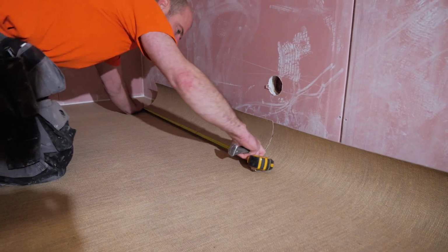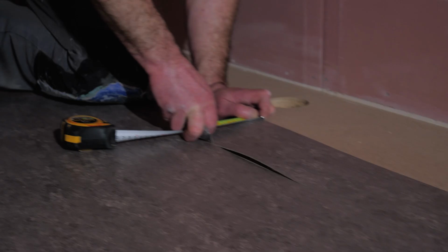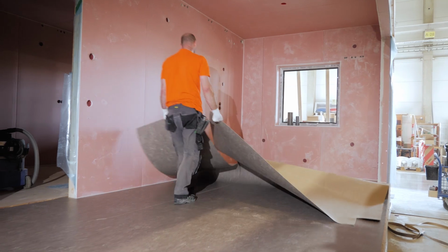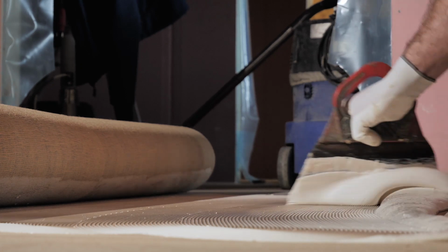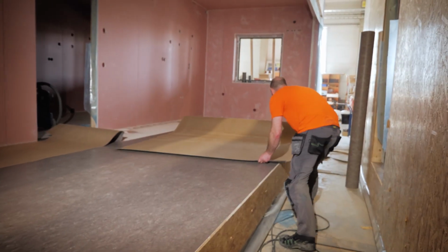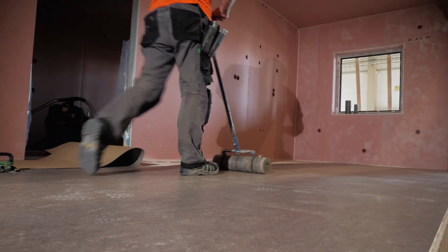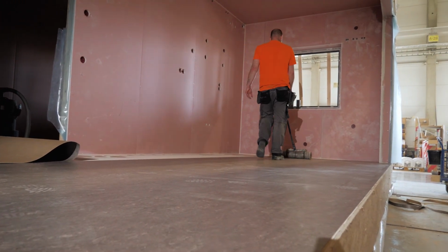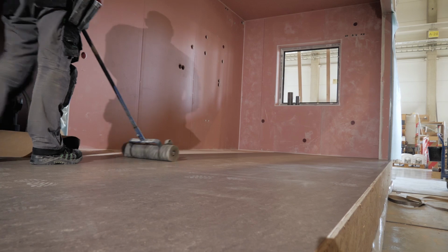Before installation of the covering, sheets of the necessary length and width are cut from the roll of material. Adhesive, designed for gluing PVC or linoleum coverings, is applied to the subfloor. Note that gluing is carried out according to the adhesive manufacturer's requirements and must be performed in accordance with the company's work instructions. The adhesive joint must remain strong, so the floor covering sheets can be pressed firmly against the subfloor. A heavy metal roller is a good tool for rolling the floor covering, which firmly bonds the covering to the subfloor.